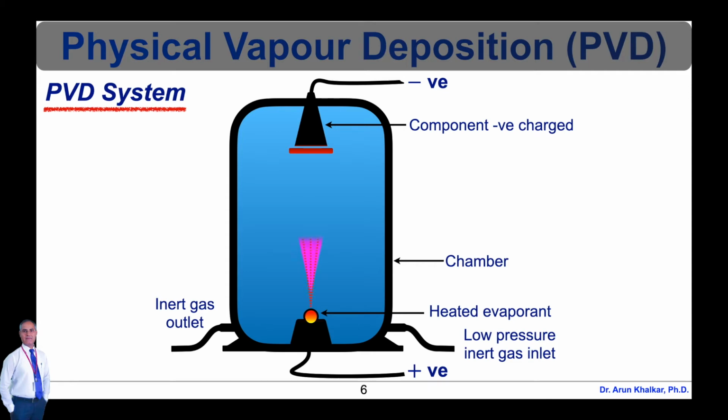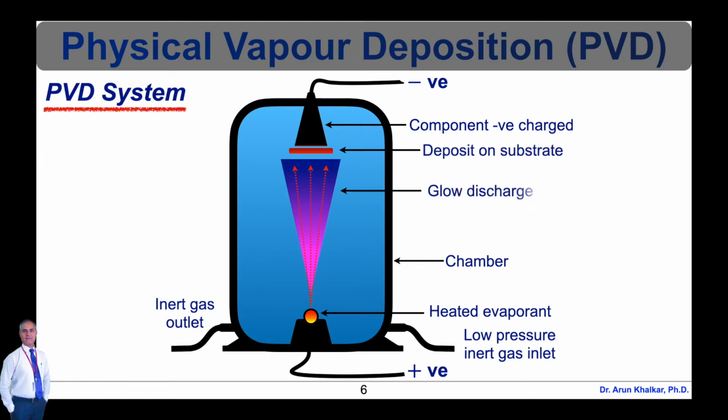A high energy source is provided to the target material, so atoms are vaporized from the target surface. Then the vaporized atoms move towards the substrate surface placed in the chamber. The reaction occurs when the deposited material is a metal oxide, carbide or nitride, otherwise it will not occur. The vaporized atoms reach the substrate surface and are deposited there in the form of a thin layer.